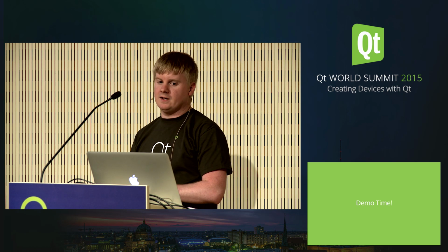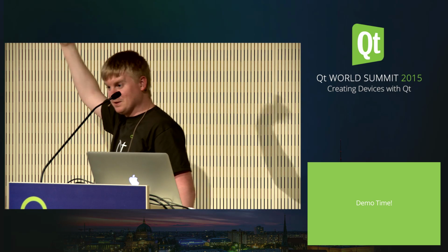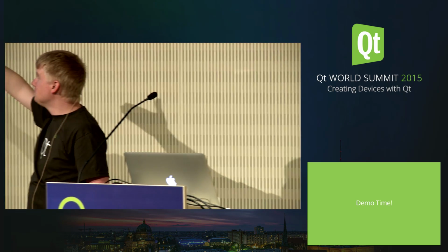This is the location on your host machine you'll actually be installing the Qt libraries to when you run make install. And this is almost always going to be inside of your sysroot. So the ext prefix will be wherever your sysroot is located that you're building against, plus /usr/local. So it's sysroot plus target prefix. There are very few circumstances where it will be something other than that.